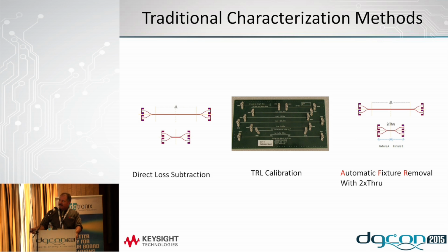And this right here could be the test fixture that you use to subtract from the complete channel. And what the result would be is the delta L. Okay, so this is just a very straightforward, rudimentary direct subtraction that we'll talk about a little bit more.